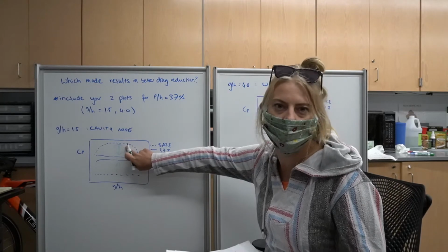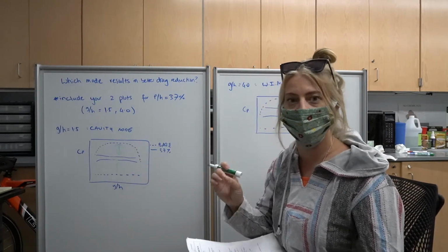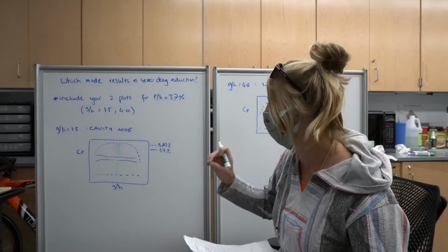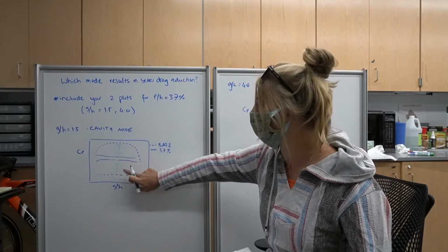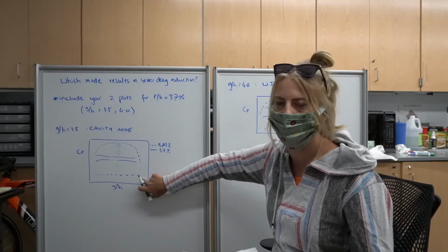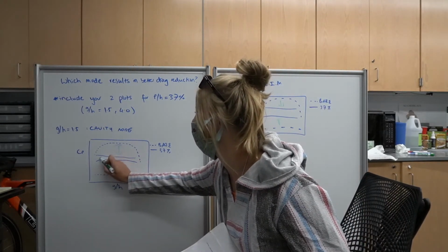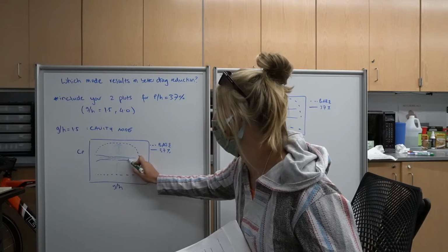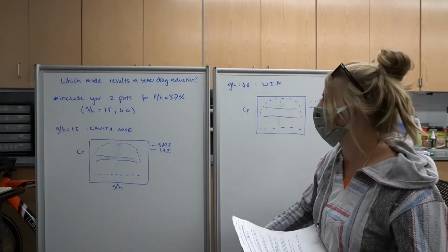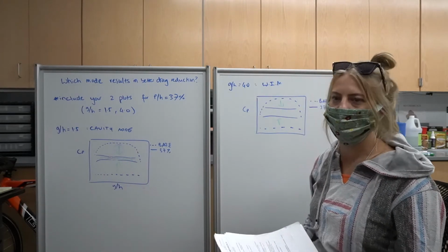So the front face, as you saw from Jay, is going to decrease dramatically because of those recirculation vortices in front of the cylinder. And then the rear face is also going to increase relative to the bare cylinder due to that weaker vortex wake. And you can see here, this area in between the front and rear faces is going to be our CD, because we know that our CD is the area between our CP front and CP rear.